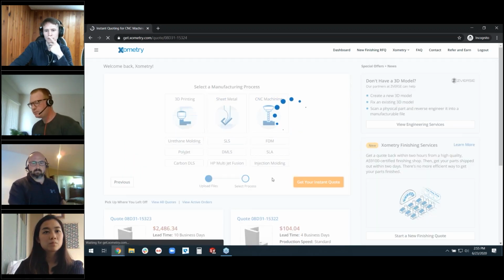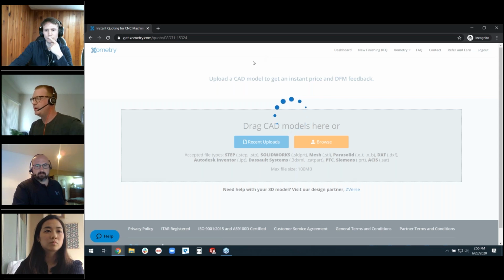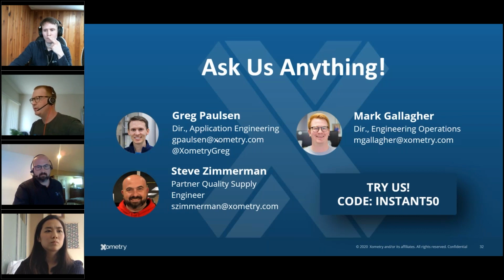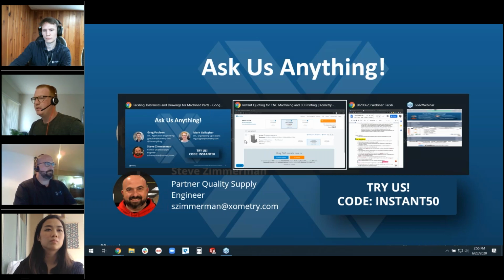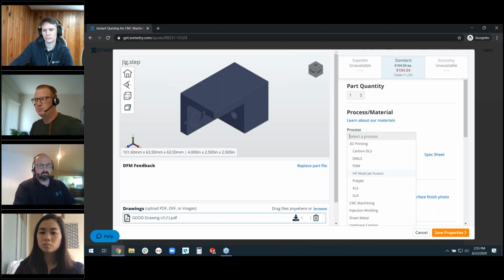A lot of heat treatment can either occur on raw material before we start machining or on finished product after machining. And then sometimes we have to even go through interim heat treatment steps, either stress relieving or hardening, and then final machining if tolerances apply after heat treatment and things like that. So my recommendation would be, for the most basic heat treatment operations, maybe you just want a steel part through hardened to like 50 Rockwell or something like that.